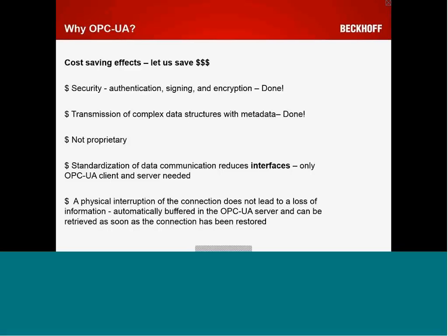In the old days, not that long ago, if you lost a physical connection, so I had an OPC server serving up data to a database, in the classic days, if you lost that connection, you lost the data. But when I had a UA server talking to a UA client, which was then stashing data away, I lost the connection, and when the connection was reestablished, boop, boop, boop, boop, all the data that happened while it was down was automatically filled in. It absolutely blew me away because I didn't enable it. I didn't try to do it. I wrote no code.